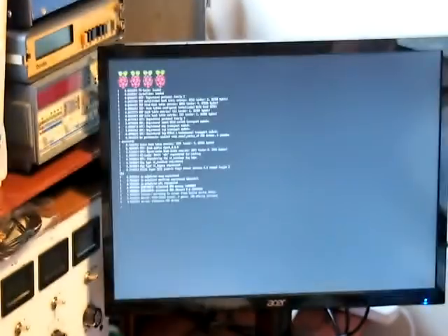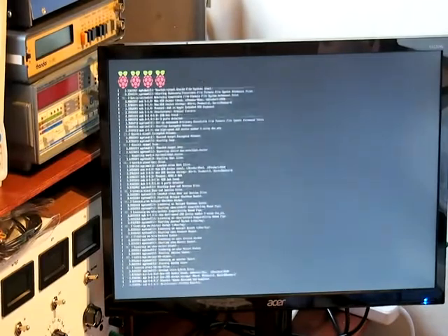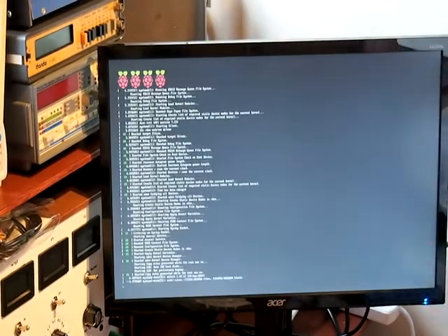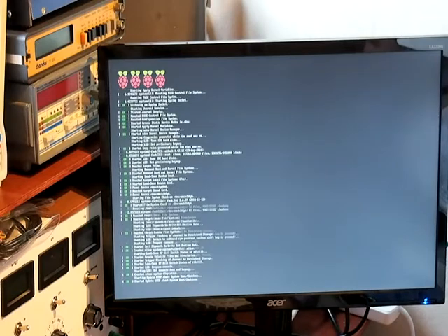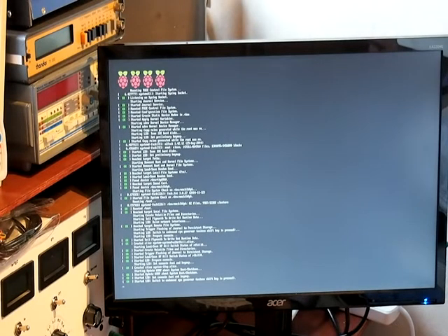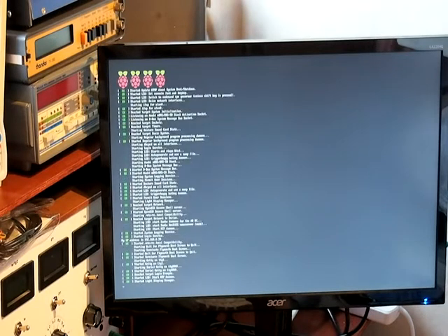And here the Raspberry Pi is booting up. We verify that the power supply lights are on for the 12-volt power supply for the Whisper receiver, and that on the GPS interface box the light is flashing about once per second. We'll just wait a few moments for the Raspberry Pi to boot up. It will boot up and automatically log in as user Pi with password Raspberry into the desktop Windows system.